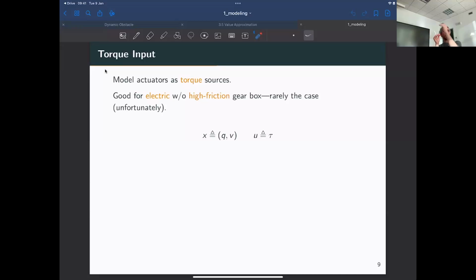And if the torque is higher, the torque you see at the output is the torque you generate minus the friction torque. The problem is that this friction torque may depend on the position of the joint. It may depend on the temperature of the robot, the temperature of the environment, the humidity of the air. So it's something that you cannot really model well. You can trust me on that because I've tried for years to model it and I failed miserably.